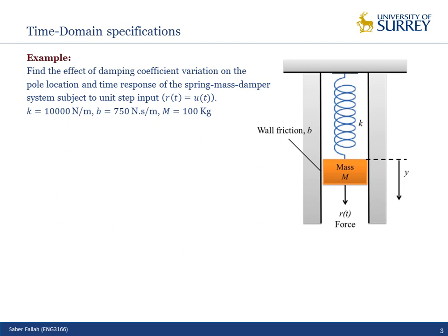What does it mean, passive control? Passive control means that you tune or adjust the time domain response of the system by changing the properties of the system. For example, the stiffness, the mass, or damping coefficient. You can actively control a system if you use an additional force or an external force to control the performance of the system. Okay, now look at this system, a spring mass system.